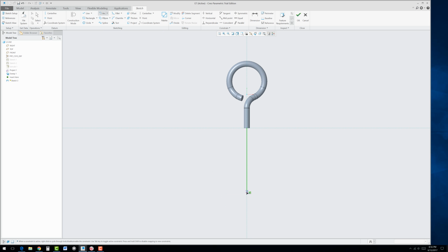So this is going to be 45 degrees. The reason why we're putting this in is our goal is to create half of this bent wire and then mirror it over to the other side. And we're making it 45 degrees because it's a 90 degree elbow. Okay, now we could go ahead and hit OK. And we have our wire again.